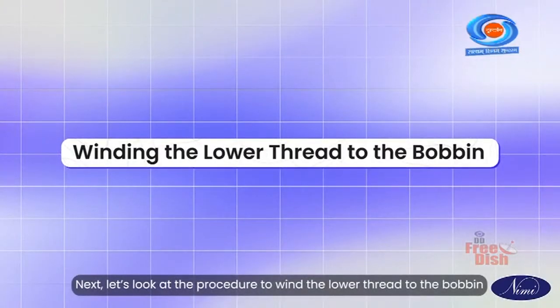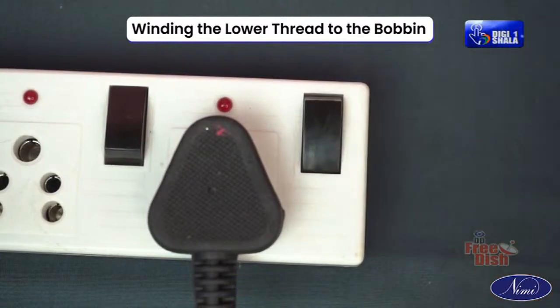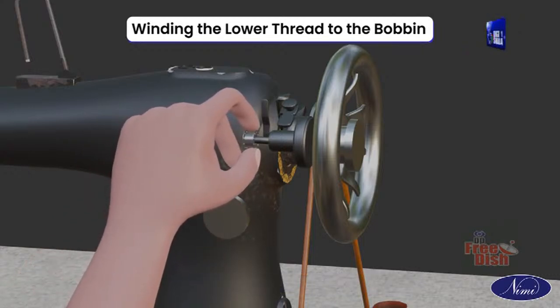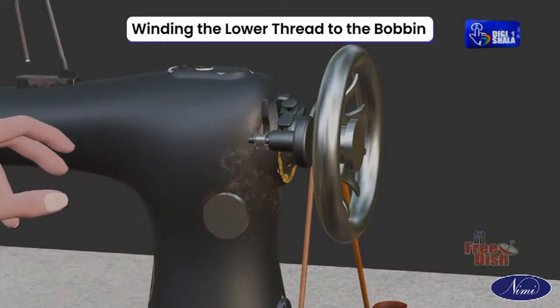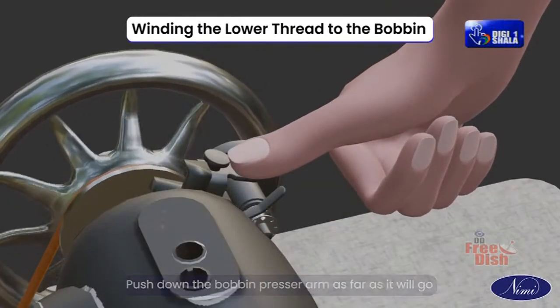Next, let's look at the procedure to wind the lower thread to the bobbin. First, turn on the power switch. Place the bobbin onto the bobbin winder shaft. Push down the bobbin presser arm as far as it will go.